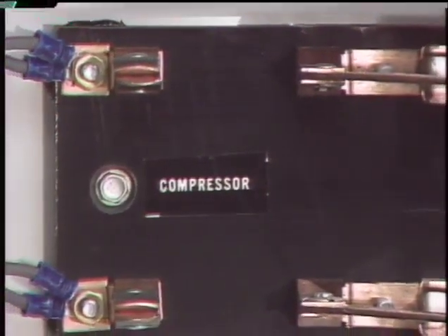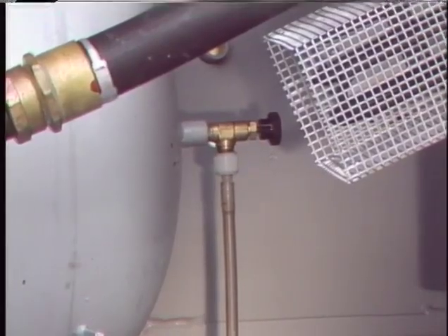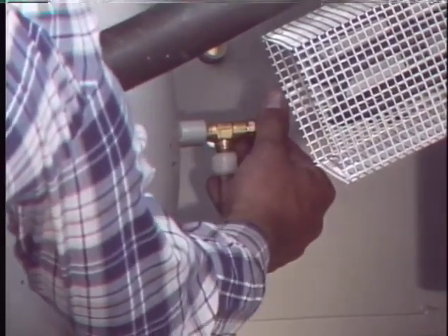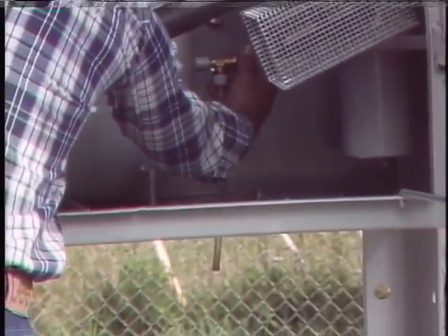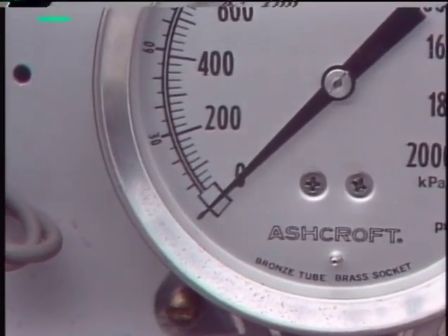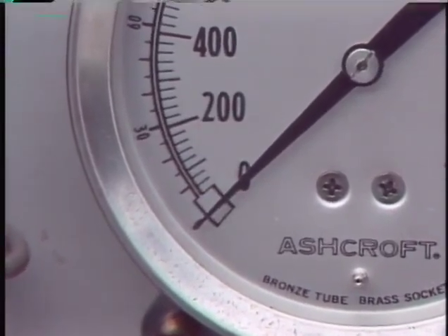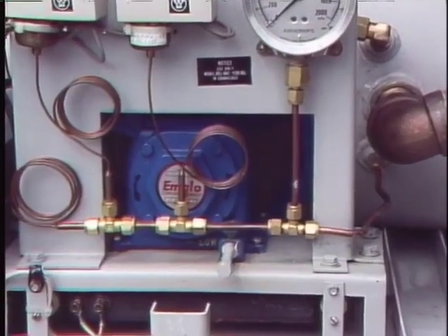Some pneumatic mechanisms don't have an isolation valve. Instead, the compressor control circuit is checked to make sure it's de-energized. Here, the compressor circuit knife switch is open, so the circuit is de-energized. Then a bleed valve is open to discharge the compressed air and bleed system pressure to zero. When the valve is open, it's normal for some water to blow out with the air. Water can accumulate in the reservoir due to condensation. After air pressure is bled to zero, the valve is closed and the operating mechanism can be cleaned, inspected, and checked for adjustments. The compressor is also serviced.